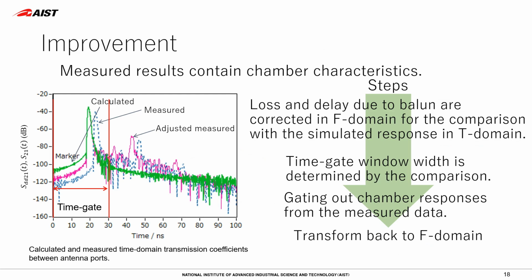In the last slide, we are happy with the successful improvement of the chamber characteristics. However, you have to be aware that the measured results we are looking at were at the single frequency point at 1 GHz. A careful look at the frequency response at the antenna separation, for example, R equal 1.0 meter, we can see wavy response with respect to the measurement frequency.